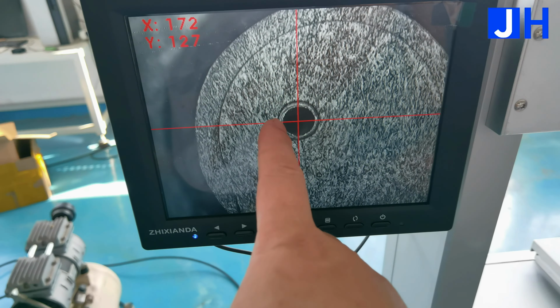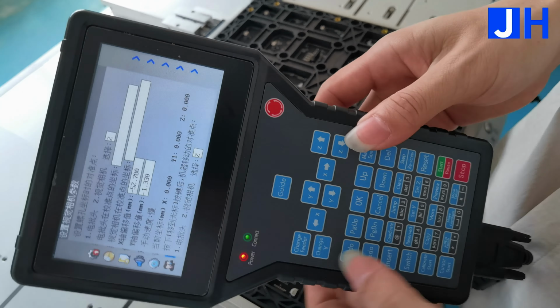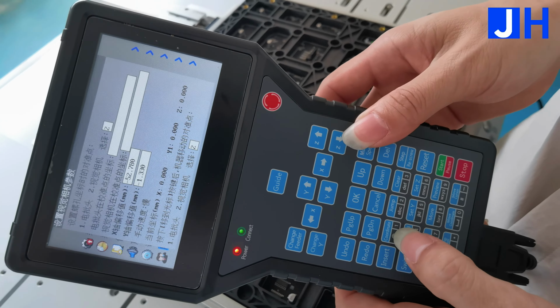Do not modify the parameter data of this page. Click down, we want to modify this moving base. We changed the moving reference from the camera to the screw nozzle, because cameras were used to locate the screw hole coordinates before, so we're going to switch to option 1, then click OK. By switching the screw nozzle, the assembly height of the screw can be obtained.